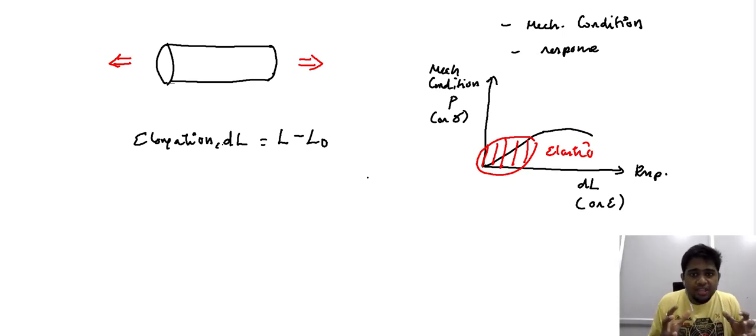So what essentially happens when you impose a uni-axial tensile loading on a metal or an alloy? The change in the longitudinal dimension of the sample is accompanied by a change in the dimension along the perpendicular direction. To make this discussion more comprehensible, let us begin by describing the different axes.